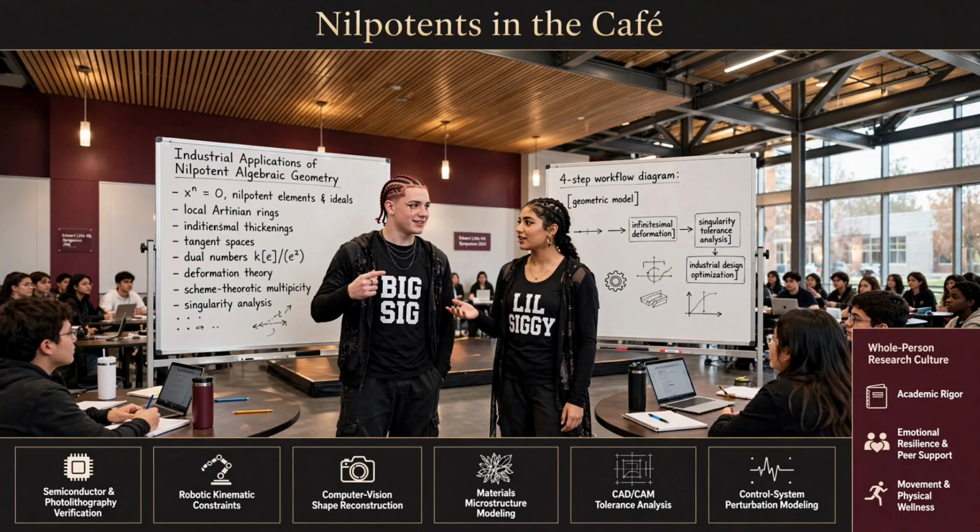Yes, please. A holonomic robot, say, a drone flying in open air or a hovercraft, can generally move freely in any direction within its configuration space. If it wants to move left, it thrusts left. Simple. But a non-holonomic system has severe velocity constraints built into its physics. These constraints cannot be mathematically integrated into simple position coordinates.